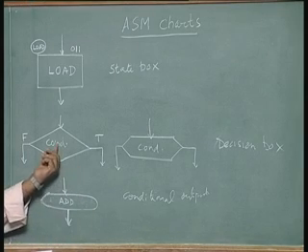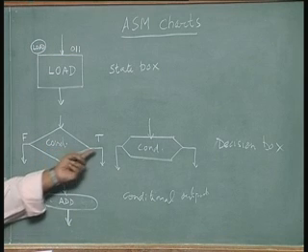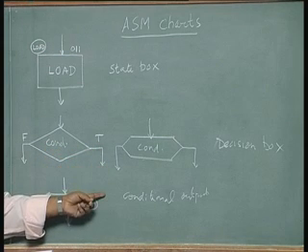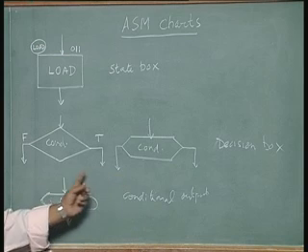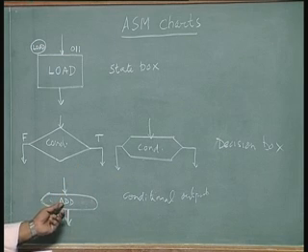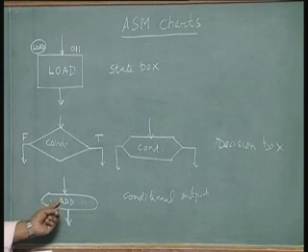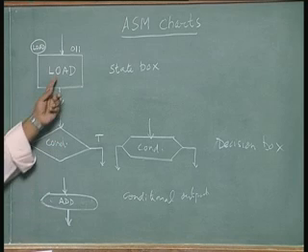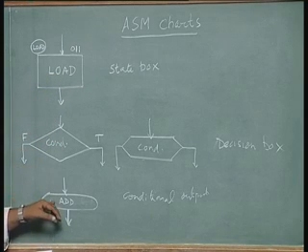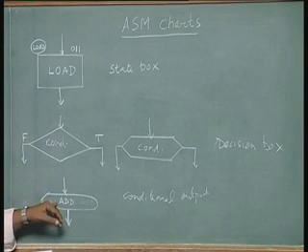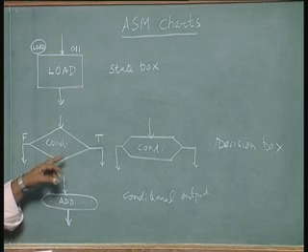You can put a condition whether the multiplier bit is 1, and before it goes to the next shift box, you can say add. So this is an output box similar to this. We generate an output; here the output generated was load, here the output generated is add, but this is done only under certain circumstances of a condition being met.